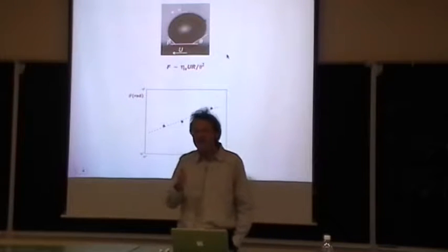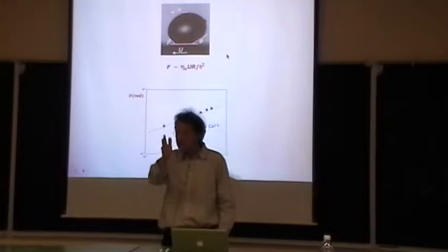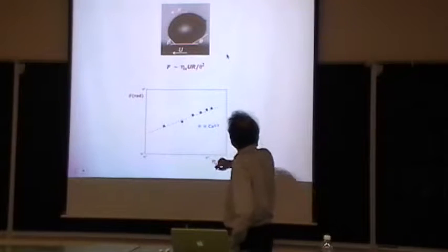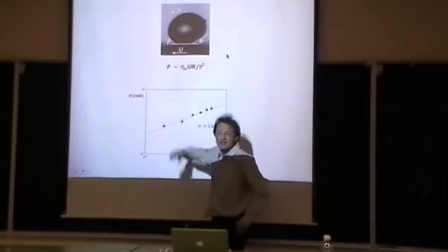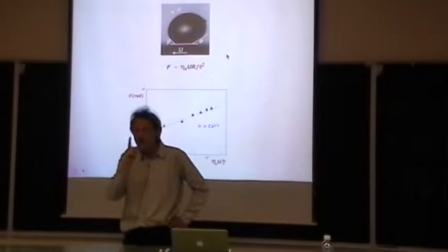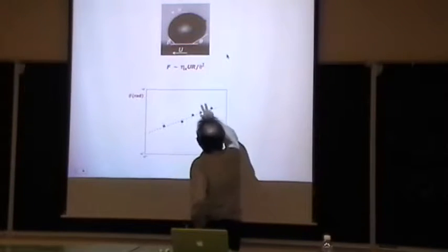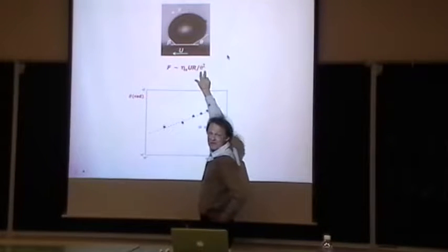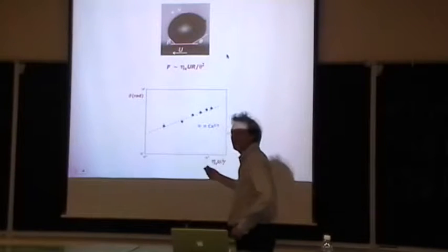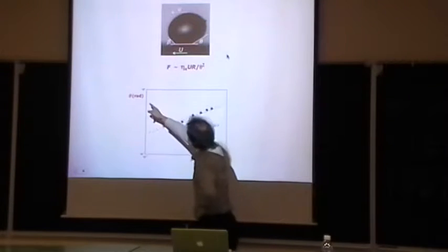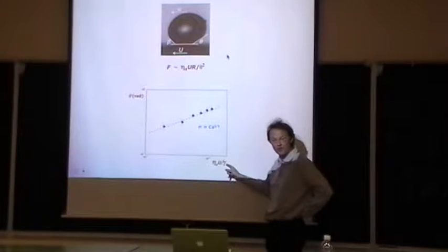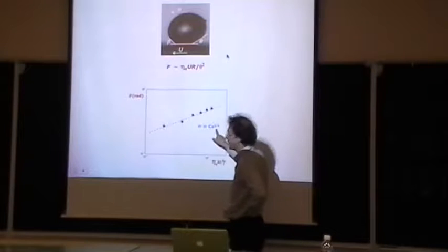Yeah, so it's very sharp, as you could guess, very well defined, and the question is exactly this one: what defines this transition? So I have no real answer to that except this possibility, which is if there is an asymmetric shape, we should have a lift on this drop. We know the formula for this lift. We even know, I think, I hope, what is theta, which is itself a function of the velocity. And I can give first an experimental answer. Theta is a function of the capillary number, which compares viscous force in the film and capillary force. And you have a scaling law, which is 1/3.